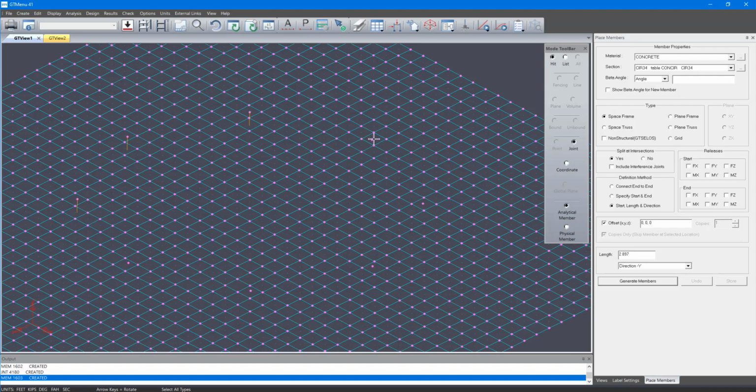and so on, okay? Now, one thing that you need to keep in mind is this is finite element analysis that we're doing, okay? Which is an approximation to the actual conditions on the site, okay? So it is not an exact science. The other thing is how the load is going to get transferred from these pedestals into the slab is, it's not going to be like through one node point. It's going to be a thick foundation, so the load is going to get distributed, okay? Finite element analysis right now is not capturing that type of behavior.